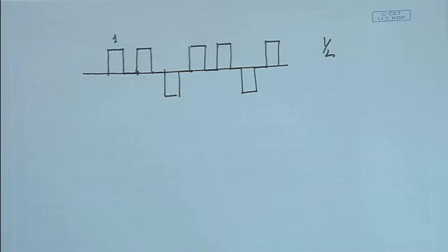So, for the autocorrelation function, what do I need to do? Of course, I can see this is a power signal because it stretches from minus infinity to plus infinity. Okay. I will do truncation and all those things, but it is a power signal, because I am not saying that these 1s and 0s start from here and end over there. I am just saying it is a continuous stream of bits which are going on.